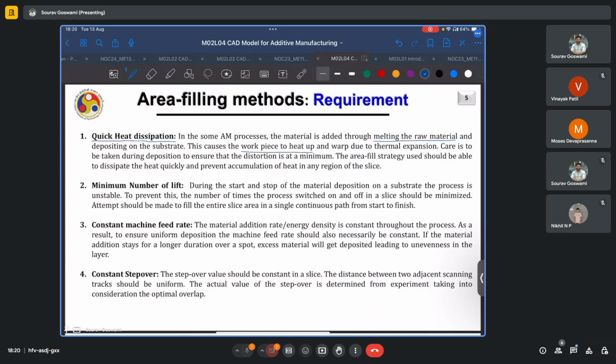and based on the thermal expansion coefficient, and if there is differential thermal expansion between the deposited material and the build plate, there can be significant warping. Even though you would typically fix your build plate to the build platform using, say, clamps or bolts, even then, I personally experienced that depending on the type of geometry you're depositing, the amount of time for which a process goes on, and the temperatures which are involved, the workpiece can warp significantly.